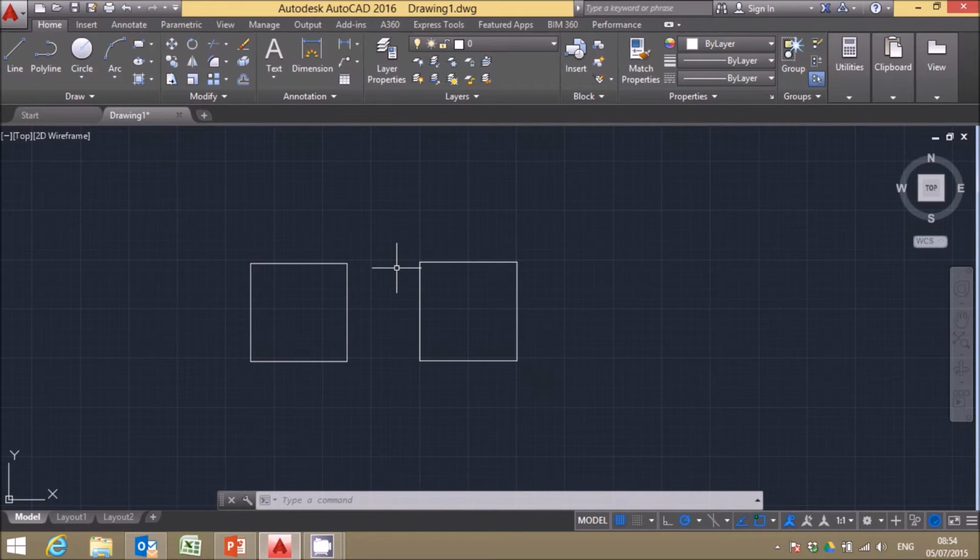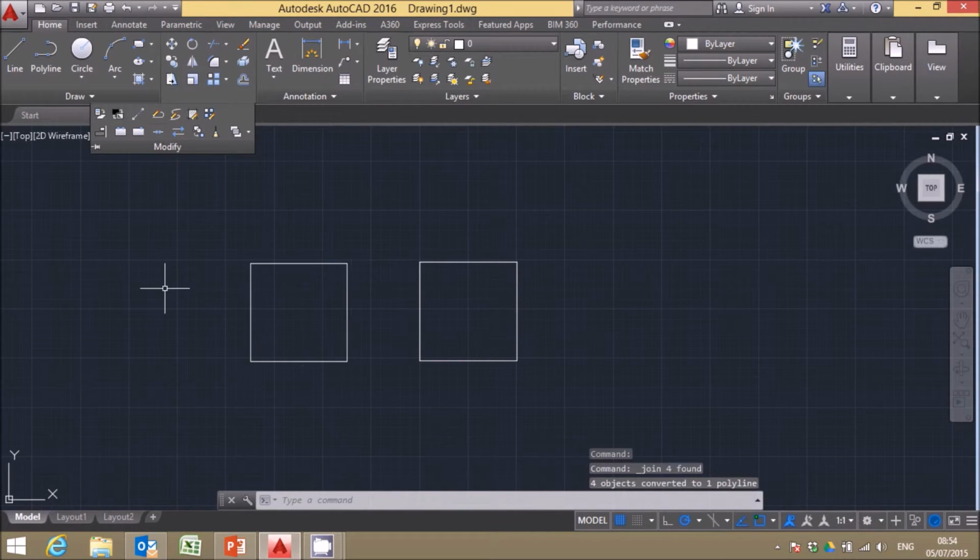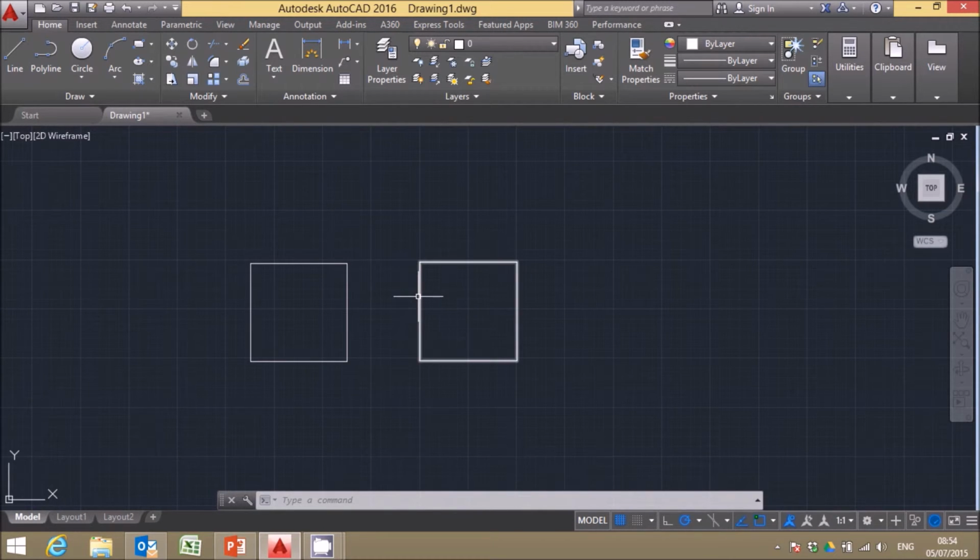So it doesn't matter which way we create it in the first place, we can make it into the other one if we want to. Here I drew it as individual lines and turned it into a polyline. Here I could have drawn it as a polyline, and clicked on explode to make it into individual line segments. Essentially, whichever one is quicker when you're drawing is what you should use.